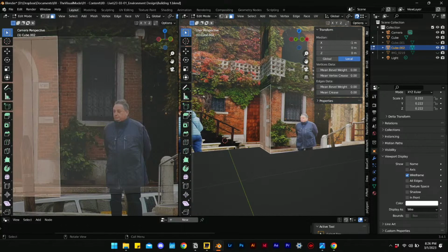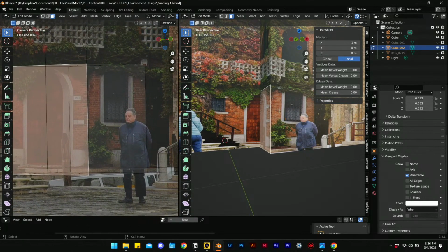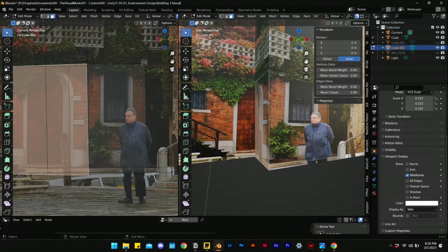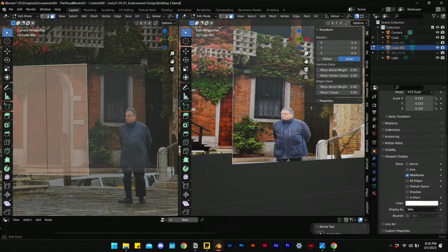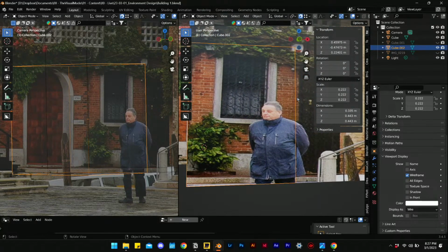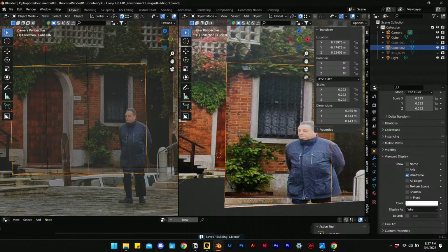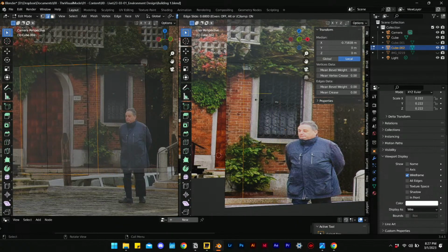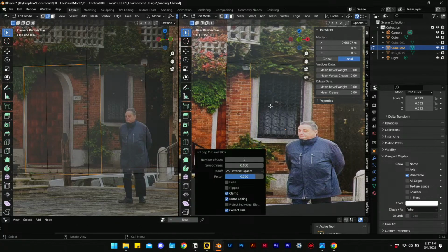We can select this face here, and I have to pick a cutoff point for that corner. So I mean, it's pretty fine there. Actually, I'll just leave that where it is. Just have it meet the corner and then having it meet the edge right there. But I want to meet it in perspective, right? There's a good reason for that moving forward. Anywho, I can now just work within this one cube. I can do Control R to add loop cuts. So I can make sure that I get the window frame now.